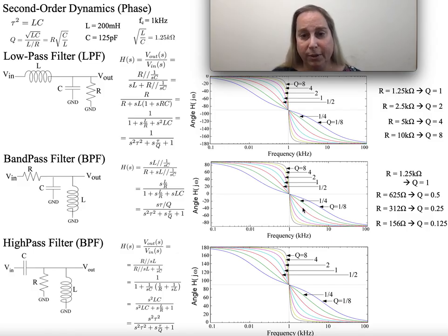And at Q equal to 1/2 is the double roots, and so it has a very smooth, almost perfectly smooth trajectory. When I start going to higher Qs, this gets to be higher and higher gain. And so what I'm going to see is that it keeps going in height. It looks like it's going to be flat here. So 1/2 is that special case where it looks like a double root, so nothing is moving. So what do I get from higher gain? I get 1, 2, 4, and 8 gets rather steep here. In fact, notice how fast this shifts from 8 from the top to the bottom curve.